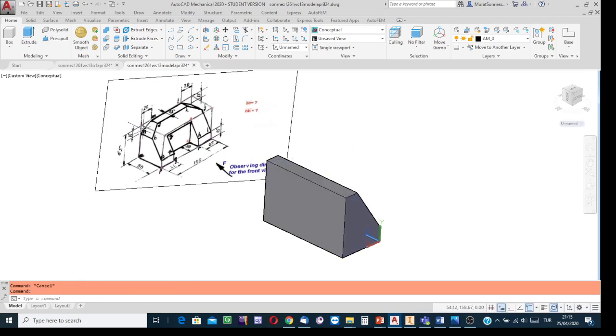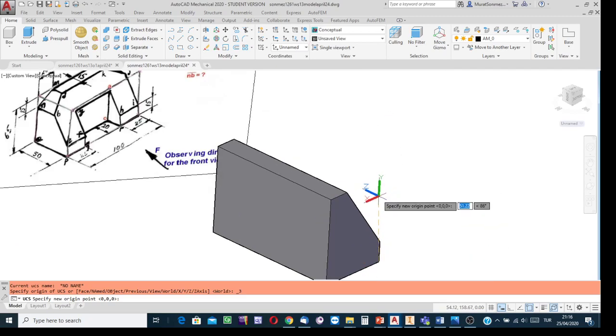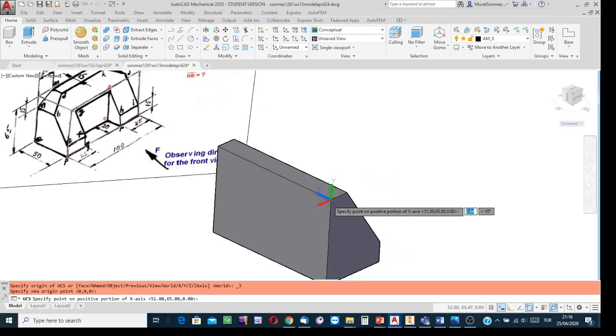Now the edge view of the trapezoidal surfaces is to be constructed on the backside surface, because those surfaces are perpendicular with respect to the backside. The XY plane must coincide with the backside surface. So one more time, apply the moving process for the coordinate frame. The 3-point method is my favorite method. I clicked on it. I'm going to locate the origin at this corner.